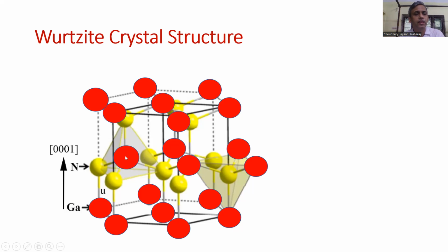And you'll see that, for example, in these crystal structures, this is responsible for spontaneous polarization in these materials. We are not so much concerned about that in this talk, but there is piezoelectric polarization, and then there is strain. The strain along the different axes is affected by these bonding configurations, and the strain can and does affect the gyromagnetic ratio in these materials.